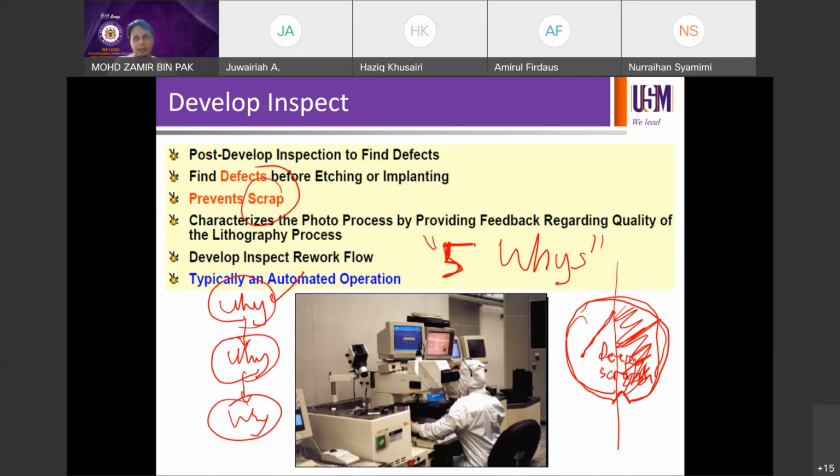Okay, you start to suspect it's one-sided somewhere. Then you do troubleshooting, and you find that the wafer is slanted on the hot plate. Then the second question is, why is it slanted on the hot plate? Okay. When you enter operations in the industry, the troubleshooting will be very structured. There's no room for you to wander around troubleshooting, and there's always a structured kind of troubleshooting.